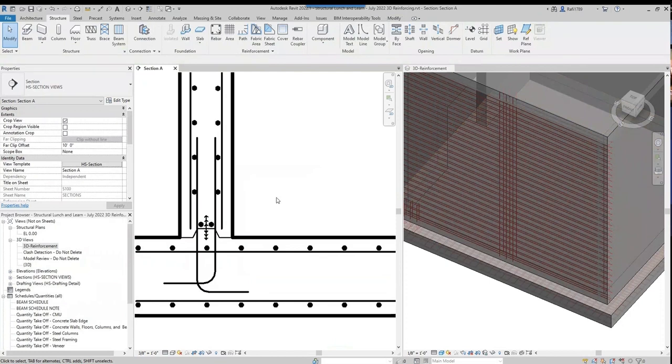Now, I will put that with a caveat, right? If you have a complex structure, you have a lot of walls, you have a lot of sections, I think it's absolutely worth the time to reestablish that constraint. Why? Because as things change, you've got to make your way through 14 sheets of sections to find every single location where your splice is no longer showing accurately, right?